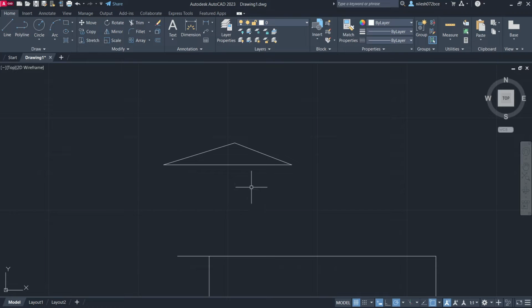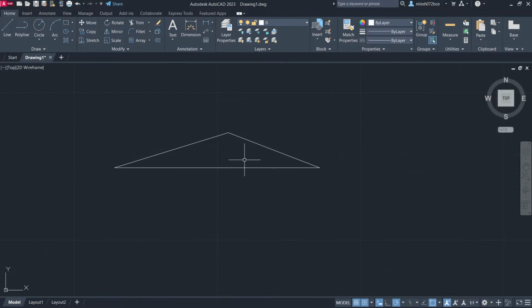And now if I want to create the same thing by turning it on, you can see the snap mode is now turned on. I cannot create again. Suppose I want to create from here. Let us again go to line command, and now I cannot choose the intermediate point here because it restricts cursor movement to specified grid intervals, and now it will only snap the grid intervals, the rectangular intervals. You can see here I cannot start my line, or I cannot create any point in the intermediate points of these intervals.